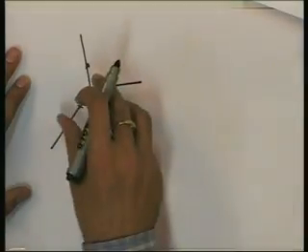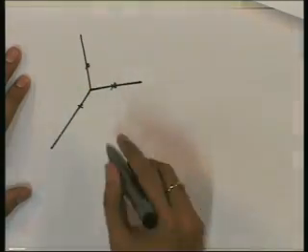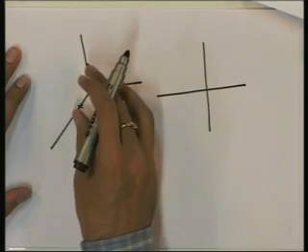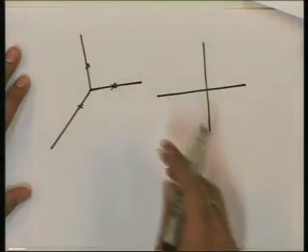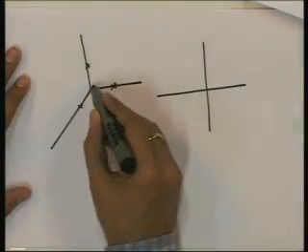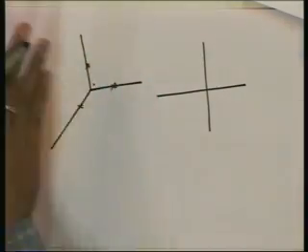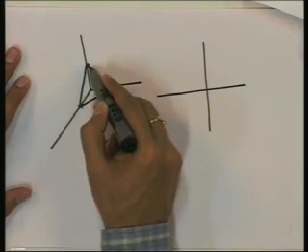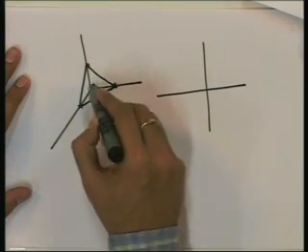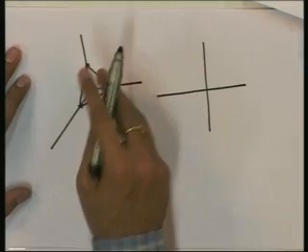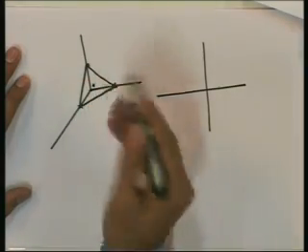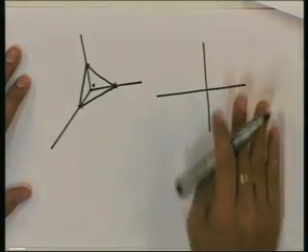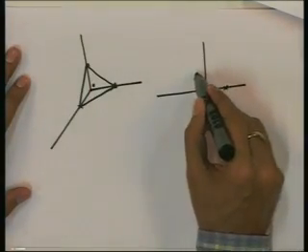Now by translating and rotating, we can bring this into 2 dimensions. So this is 3 dimensions. We can translate the signal set and rotate it. If you join these 3 points, there will be a plane, and there will be a triangle on that plane joining these 3 points. Take the centroid of that, bring that centroid to 0, and rotate the plane so that it lies on the xy plane only. Then we will get a signal set like this.